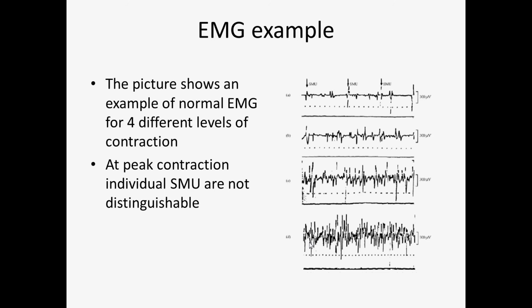There's only one way, unfortunately, to distinguish between EMG, a peak contraction or a large contraction, and noise. You need to observe the muscle or have another way of observing the contraction, for example, using an accelerometer or other sensor that can measure the vibration of the muscle.